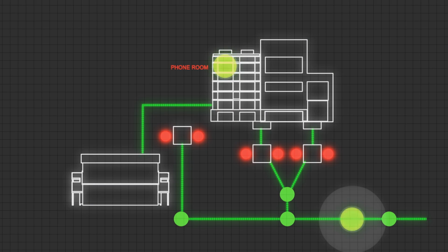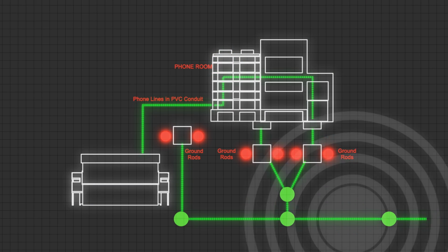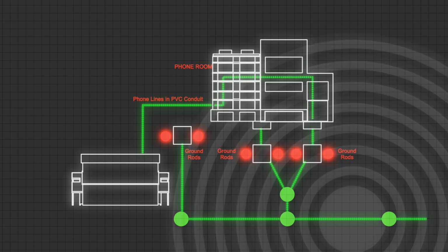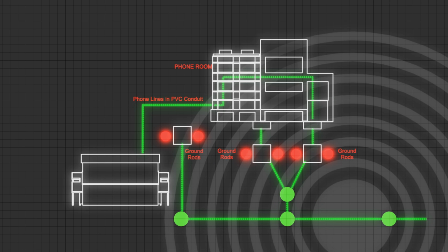The phone equipment was in the middle of the building and there wasn't a hole in the roof, so what happened? Well, it turned out that after analyzing the problem, we found that the lightning likely hit the hill behind and to the side of one of the buildings. When that happened, that impulse of current entered the ground and caused a high voltage gradient near our two buildings.